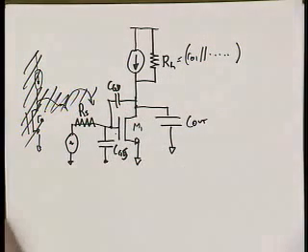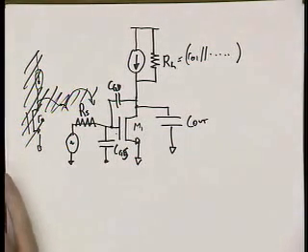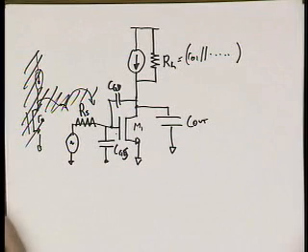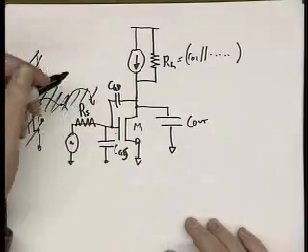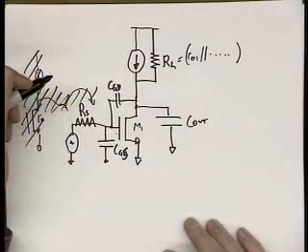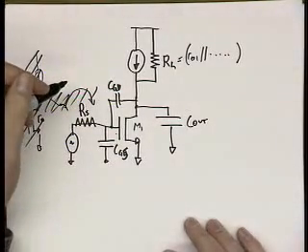Now the question is, what are the poles of this guy? You can do a lot of analysis, and the analysis gets very tedious very quickly using small signal models. If you do that, a suggestion that I always follow is to replace all the resistances, impedances and capacitances with generic impedances.